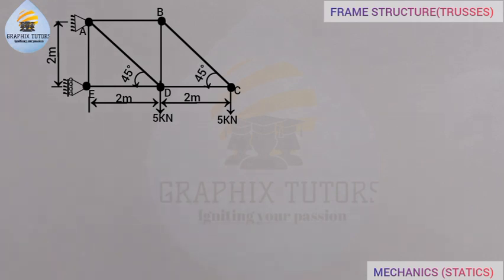free body diagram, right? Now if I draw my free body diagram, I'll be having this, the force acting at A, the hinge support. This is hinge support, it will be having two reactions, right? So the support, when you convert it, you'll be having two reactions. So this is what we have here in this direction and in this direction, right? Now, if you look at the other support here, which is the roller support, it will be having one reaction.